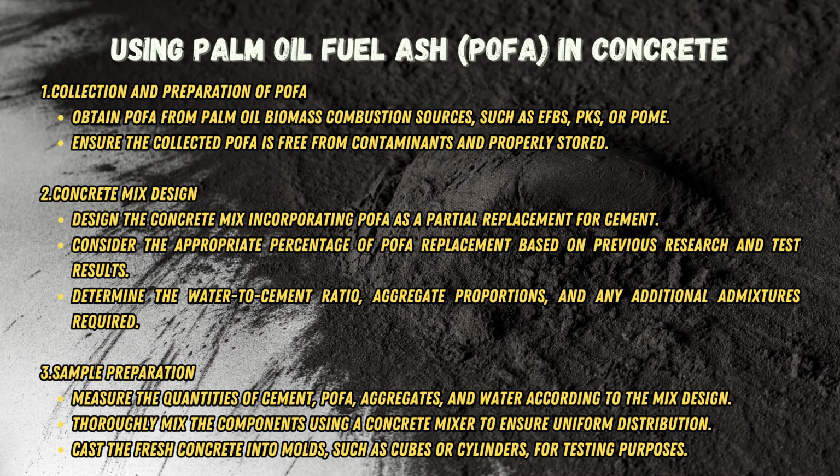Third, sample preparation. Measure the quantities of cement, POFA, aggregates, and water according to the mix design. Thoroughly mix the components using a concrete mixer to ensure uniform distribution. Cast the fresh concrete into molds, such as cubes or cylinders, for testing purposes.